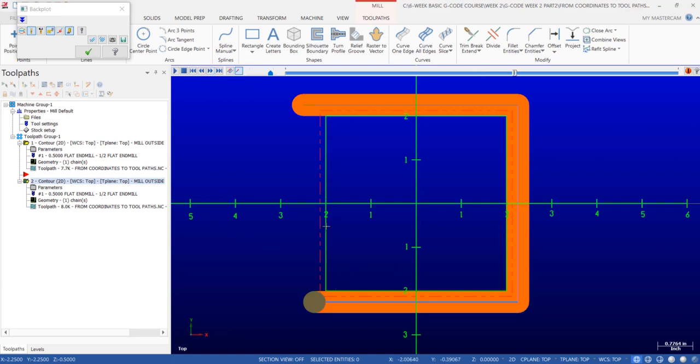Now, this is our 2 inch line on the left side of the part. Our tool is now lined up to make the next tool path. So it's sitting at X minus 2 inches 250, Y minus 2 inches 250. And then we complete the move. And it's not necessary to actually go 250 beyond the part. I could have stopped at 100 thou, but just for simplicity, we will just keep adding that additional 1/4 inch. So that is now creating a toolpath that actually leaves our 4 inches intact, but we have removed the excess stock that's sitting on the outside of the part.